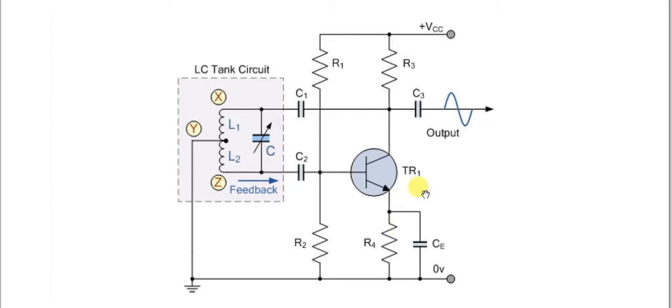Some of the voltage drops here and a reduction in the gain may be observed. To overcome this drawback, we provide a bypass capacitor. The capacitor allows AC current and blocks DC. So whatever voltage was supposed to drop here takes an easy, conducting path for the AC, goes down to the ground and is added to the output.